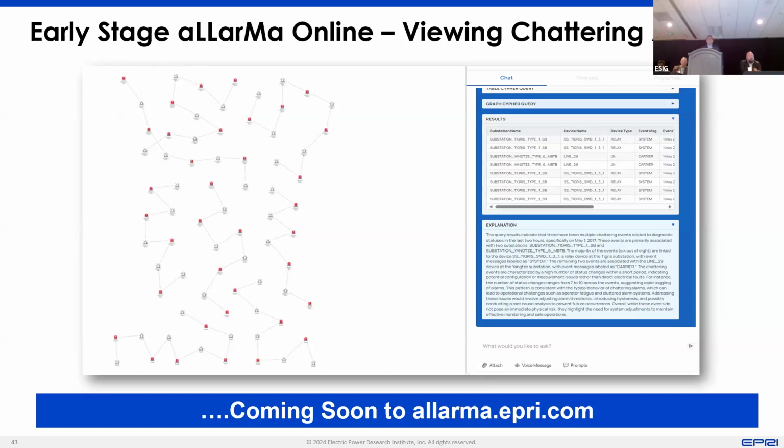So this gives us a very powerful baseline tool to look at all the operational data sets together. One quick example is, if you have a storm happening in the system, you can quickly look at those alarms and say, based on those alarms, these are the lines which are out, and it will be able to quickly tell you. That's basically what we're trying to do here: making alarm management much easier and accessible from an operator perspective, and also making sure that we have more perspective of the alarms and the network together, so that the operator can see what is going on in the system.